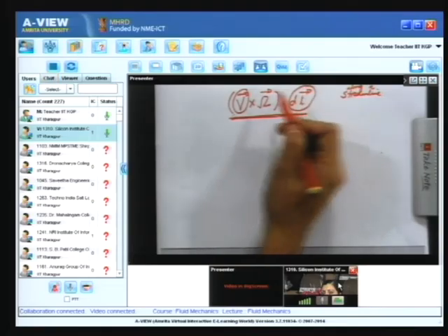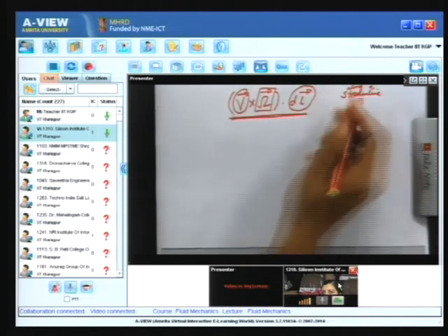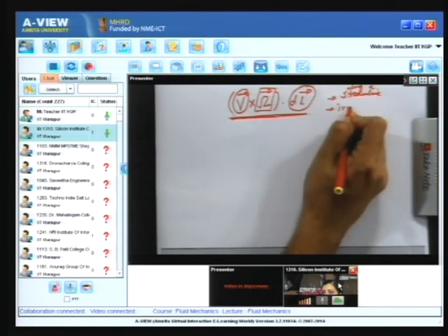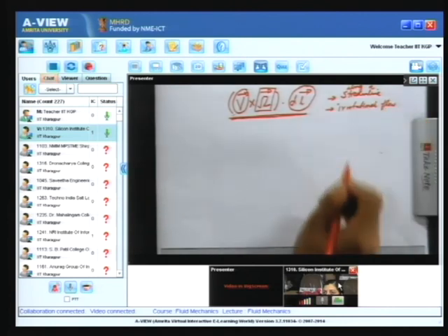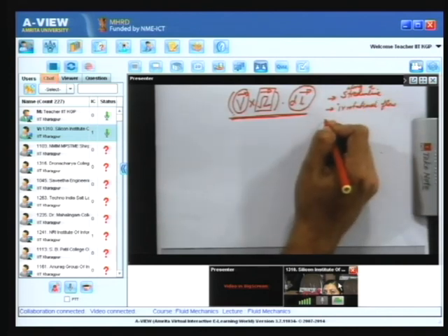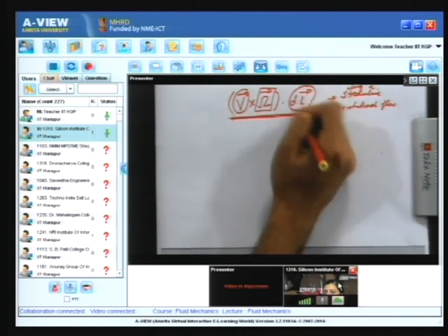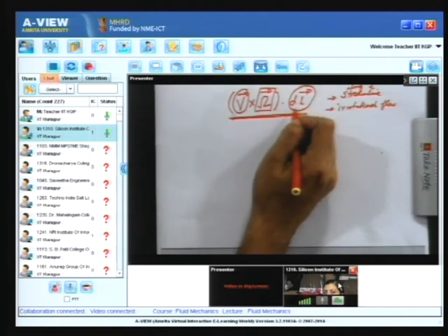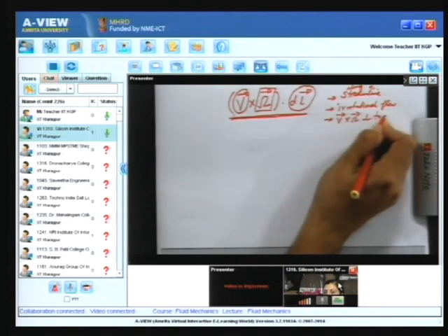For example, if the vorticity is a null vector, that means it is irrotational flow, then you can apply between any 2 points, but in the siphon usually the Bernoulli's equation is applied between 2 points along a streamline, therefore this restriction is not necessary. And the third restriction, which is not very common, is if you have V cross omega perpendicular to dl. If you choose your line element dl in such a way that V cross omega is perpendicular to that, then also this term becomes 0.